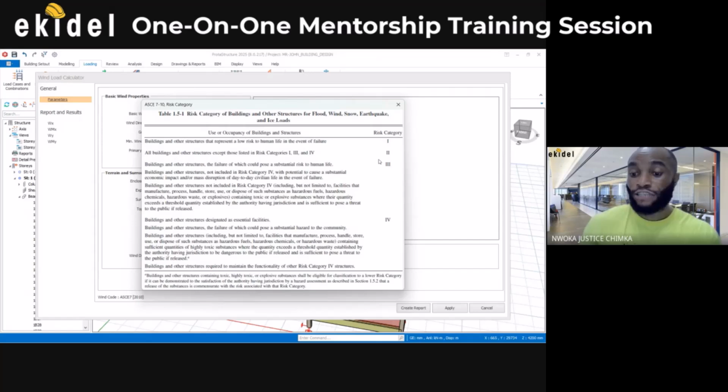Understand? Then category 2 says all buildings and other structures except those in categories 1, 3 and 4. Now let's see what 3 and 4 say. Category 3 says buildings and other structures that, if there's any failure, will pose a substantial risk to human life. For example, residential buildings fall under that. Because if anything happens, it will cause issues. For example, classroom structures and school buildings fall under that.